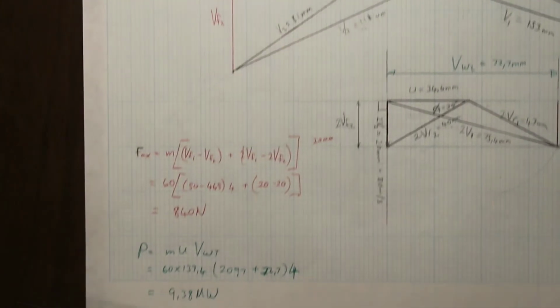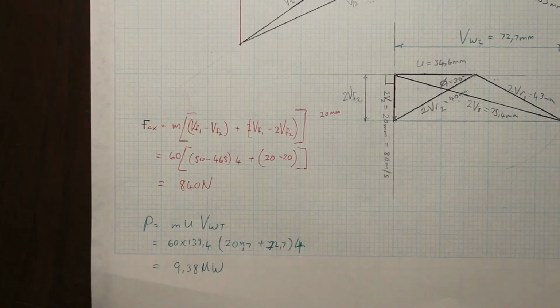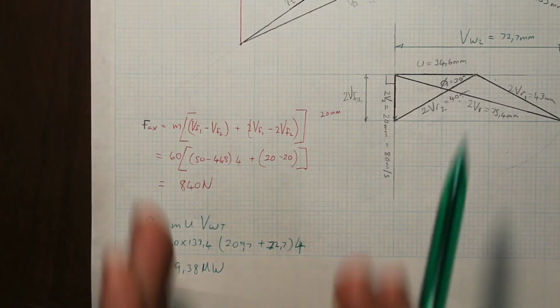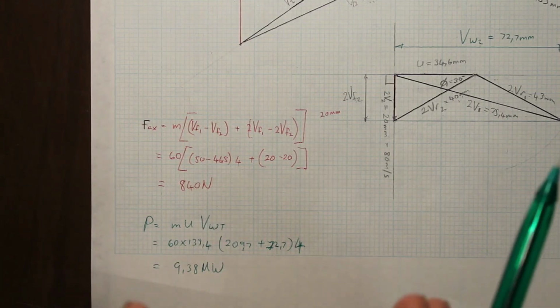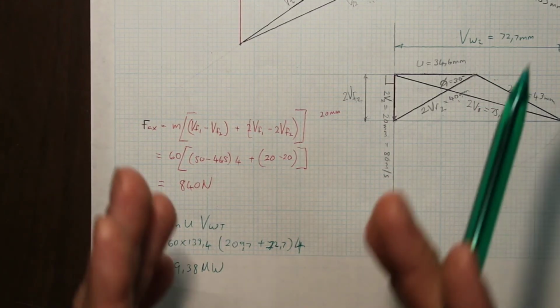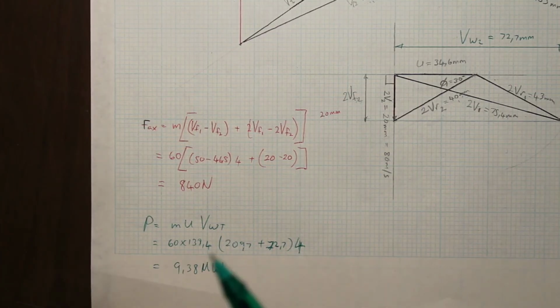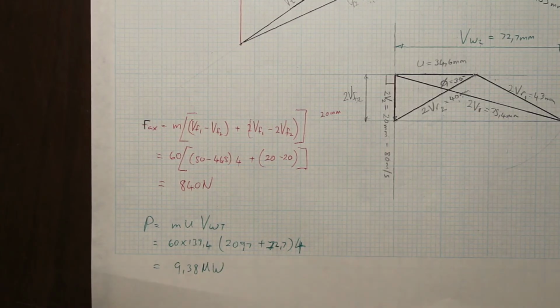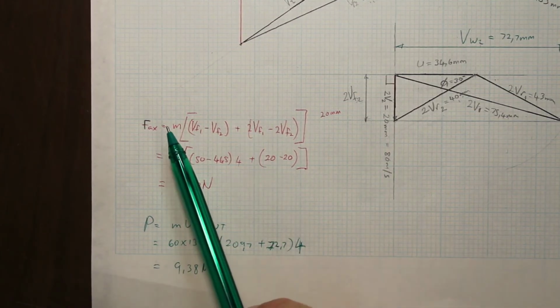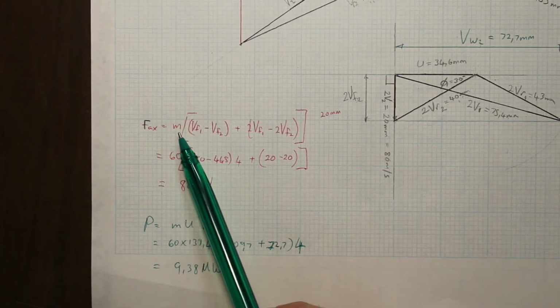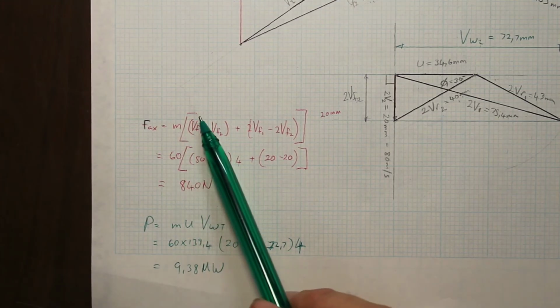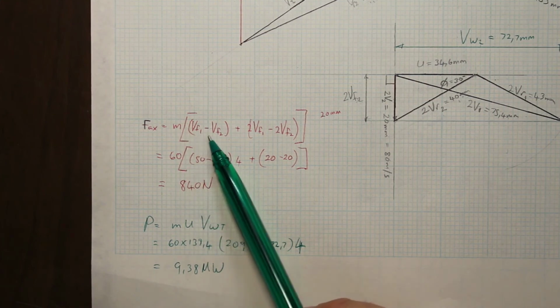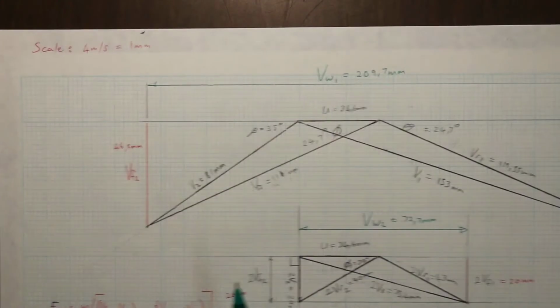Then they will also normally ask you these two calculations here. So they want the axial thrust. For the turbine, the steam is obviously flowing through the turbine, and it's putting an axial force onto the moving blades. And it's very important to know how much that axial thrust is. So here's the formula: axial thrust equals the mass flow rate, which is 60 they gave us, open bracket, Vf minus V1. So it's on the diagram here.